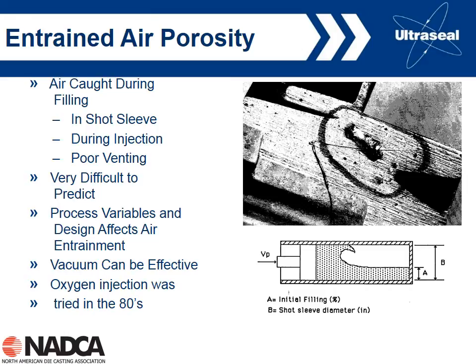And so people tried that, and it was relatively successful. I think it had a couple of problems, one of which is that you're basically replacing your porosity with aluminum oxide throughout the casting, so that's not great either. And also, obviously, there's some safety issues in terms of actually filling your cavity with pure oxygen. So that was a process that was really not that successful.